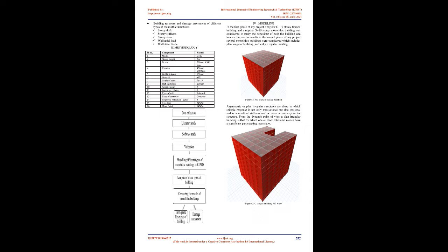Story height, beam, column, wall thickness, material grade of steel, slab thickness, seismic zone, importance factor, type of soil, type of structure, response reduction factor, live load, floor finish values. G plus 10, 3 m, 300 mm x 380 mm, 450 mm x 450 mm, 150 mm, M25, Fe 415, 200 mm, 5, 1, soft soil, concrete 5, 3 kN/m², 1 kN/m², 4.